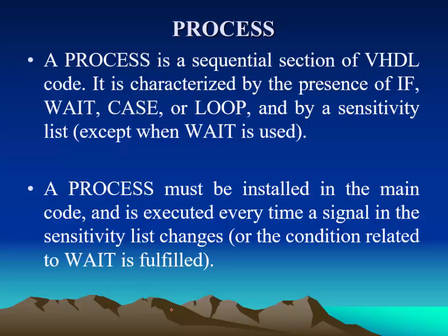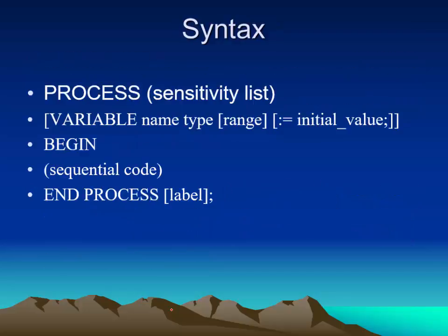So what this essentially says is that whenever we have a process, we have a list of signals, for example, one of the signals may be clock. So if the clock doesn't change, everything in that process is ignored. It only looks at a change of a clock. Reset could be another one, or clear not. So this process has these sensitivity lists right there.